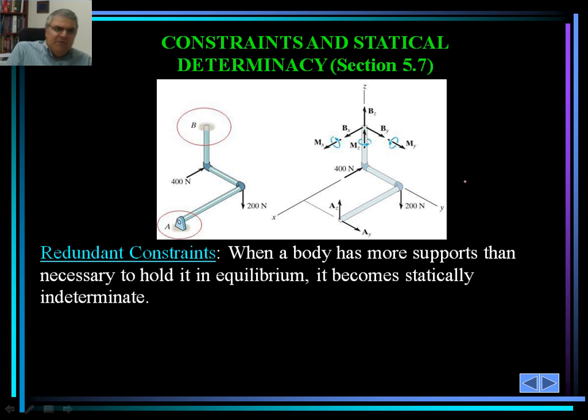So what is a statically indeterminate structure? In most of our structures, we would try to provide as much redundancy as possible, so in case one member fails, the other member can pick up the load, and primarily that is for safety and reliability reasons. As such, when a body has more supports than necessary to hold it in equilibrium, it becomes statically indeterminate.